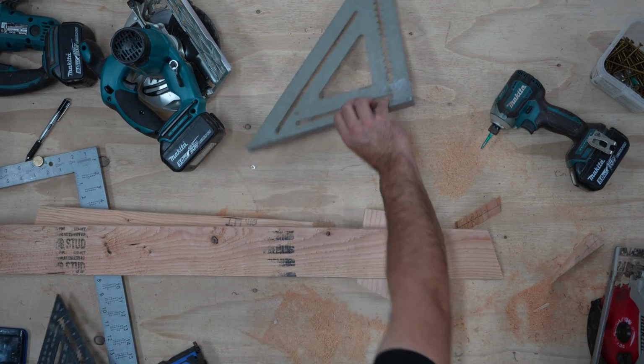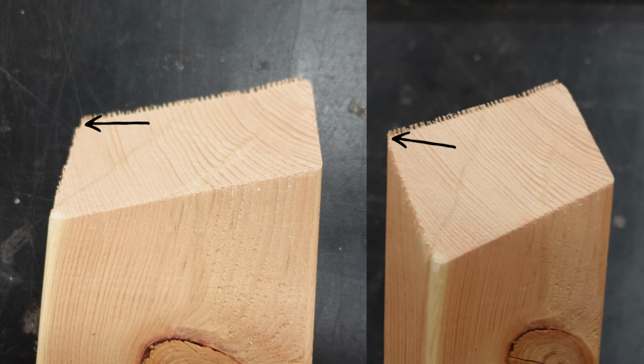The other 3 points of the compound bevel are the long short, the short, and the short long. Sometimes you may need to measure to one of these other points, so you can't always measure from the long, but it is the easiest.